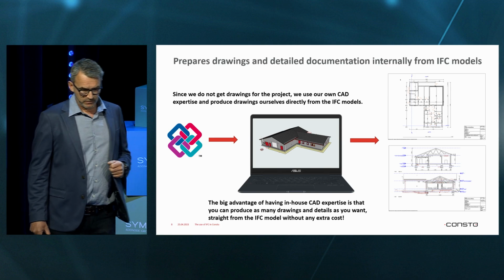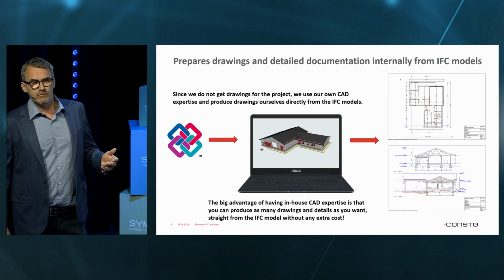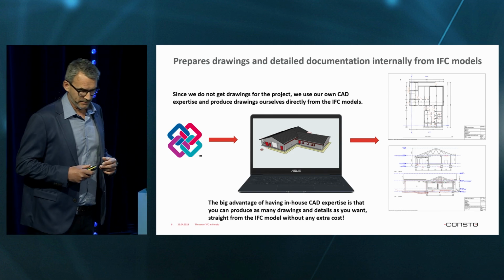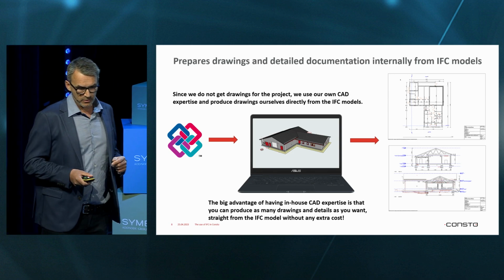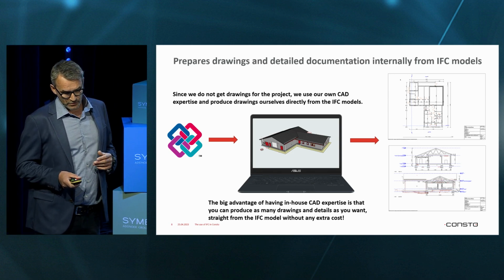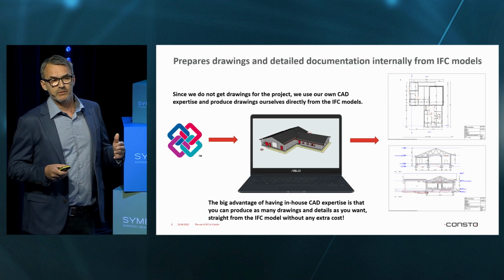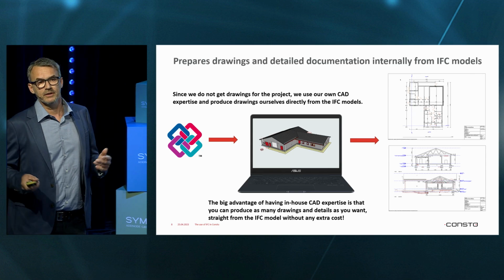But to prepare drawings and detailed documents internally from the IFC model, we moved the CAD competence into our company. Since we do not get drawings for a project, we use our own CAD expertise and produce drawings ourselves directly from the IFC model. The benefit of that is we can produce whatever drawings we want directly from the model.